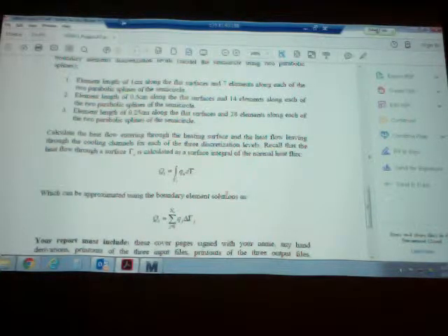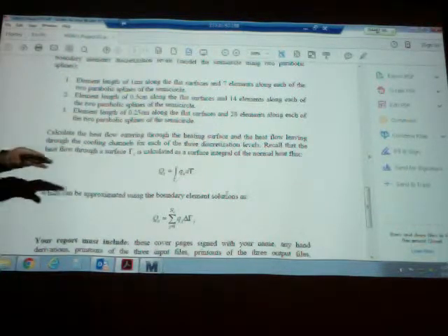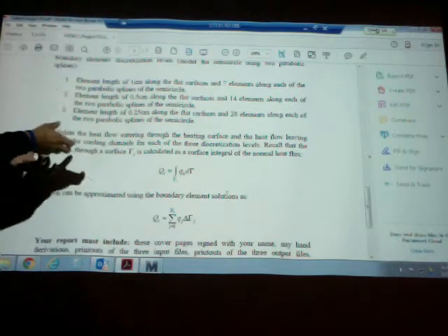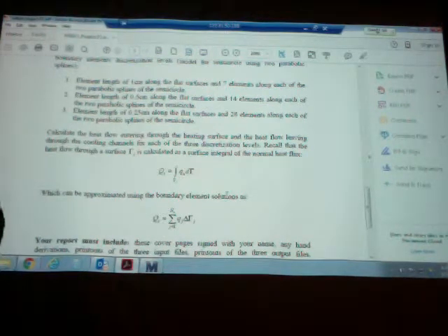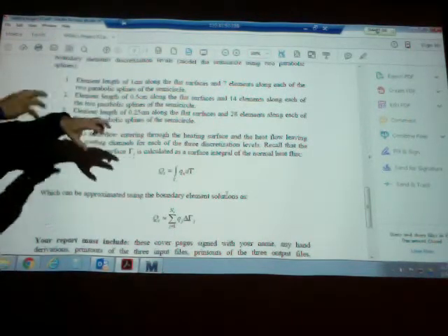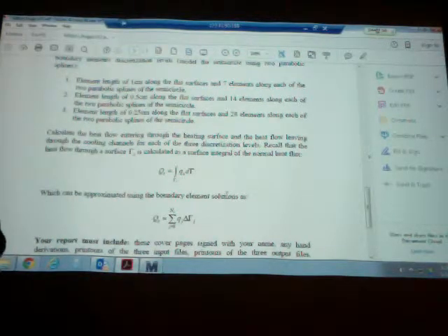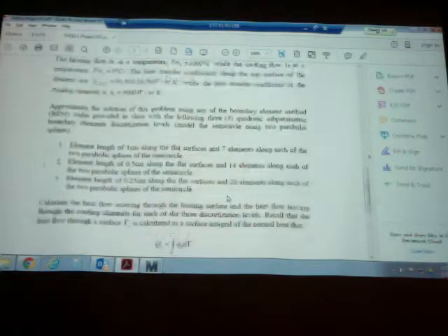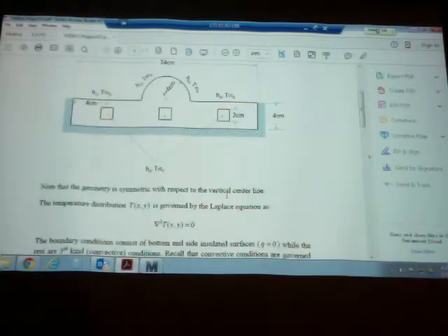But you're also going to calculate the amount of heat that is added through the top surface and the amount of heat that is removed from the cooling holes. Okay? That is a way of testing convergence, by the way, because what is the relationship of the heat that is being removed to the heat that is being added? Should be equal, right? This is a steady problem with no generation. So at steady state, those two have to be identical because the other boundaries are insulated, right?